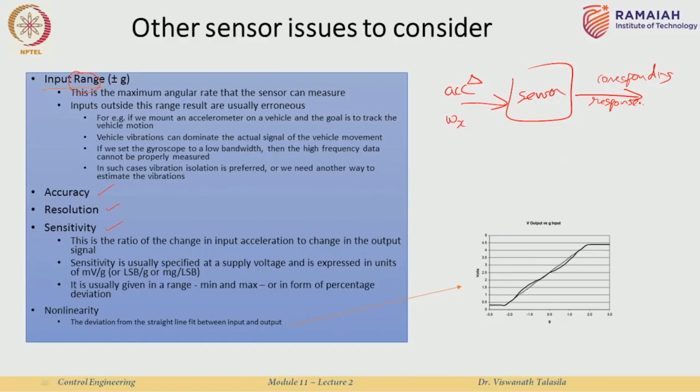However, if it takes a large input to have some amount of data coming in over here, then it means our accelerometer or gyroscope is not sensitive enough. All right, that is the basic meaning. We will ignore this nonlinearity, you can look it up in the data sheets. We expect the behavior of sensors to be fairly linear around certain operating regions.